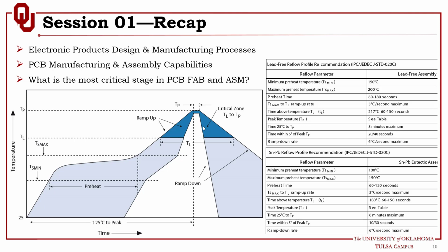And here you have the actual melting of the alloy, or the soldering material you are using, which forms the mechanical and electrical joints between the board pads and the component joints. The timing in this stage is very, very critical. A higher temperature could damage the board, and a lower temperature could also result in bad soldering joints.